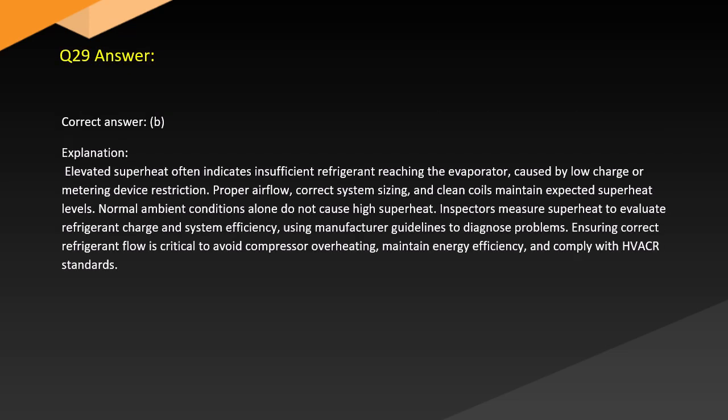Answer. Correct answer, B. Explanation. Elevated superheat often indicates insufficient refrigerant reaching the evaporator caused by low charge or metering device restriction. Proper airflow, correct system sizing, and clean coils maintain expected superheat levels. Normal ambient conditions alone do not cause high superheat.